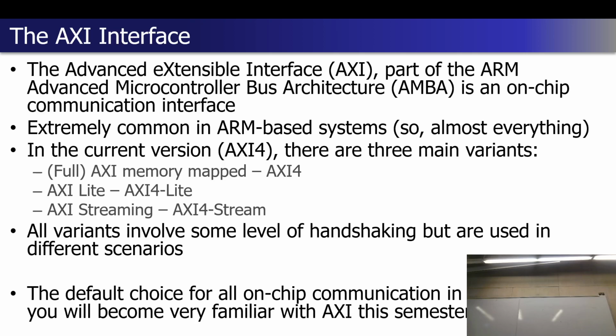And we walked through the various types of handshaking signals, and the one that seemed reasonably good for resolving some of those miscommunication issues was the four-way handshake, where we have both a request and an acknowledgement signal, request coming from the sender, acknowledgement coming from the receiver side, and we would both wait for them to go high for the start of the request and also wait for them to go back down, essentially as an acknowledgement that the request has been received.